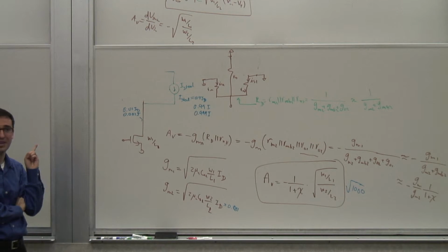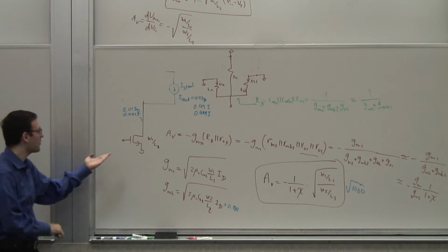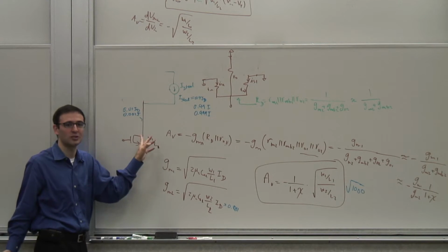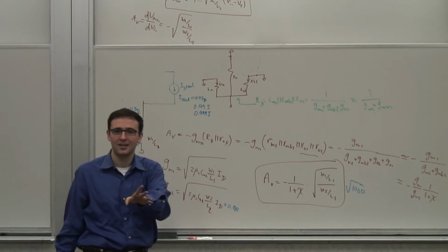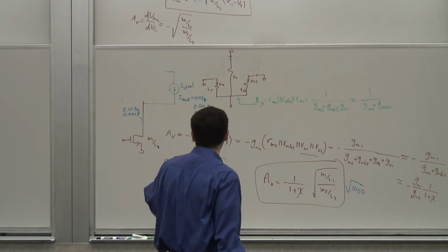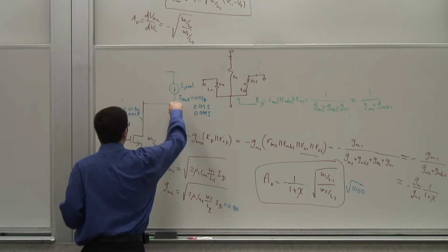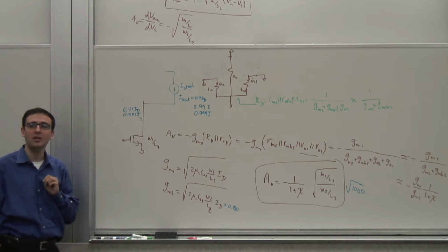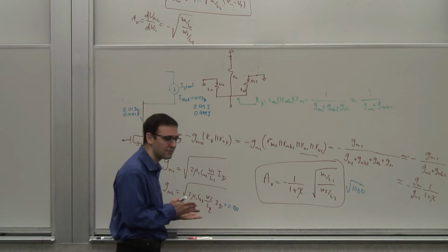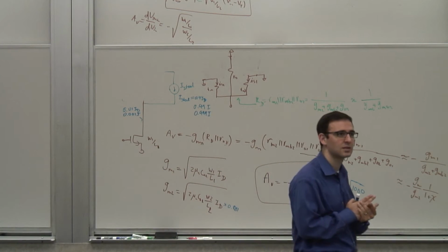This is something you're familiar with, though. This is an active load, right? In principle, this is how you can get the maximum gain out of the transistor: you load it with a current source. So it reduces to something you already knew in the limit. Now, I can't make that because I don't have an ideal current source, but I can emulate an ideal current source with something else, right? I want a stage that can maintain a constant current at a reasonably high output impedance.